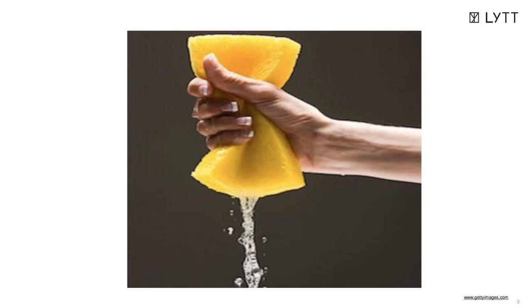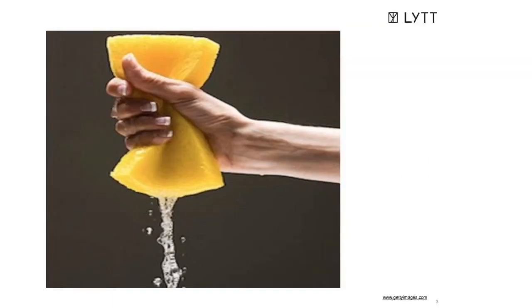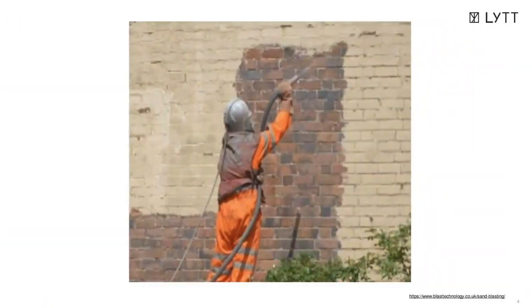Sand, as you may know, can be quite erosive, and at high production rates, sand tends to erode the piping in the wells, causing well integrity risks. You may have seen sandblasting in action, as you can see in this nice little image, to remove paints, but imagine doing this constantly from inside the pipe at much higher rates for hours, days, weeks, or even months. This obviously raises significant risks from a well integrity perspective.